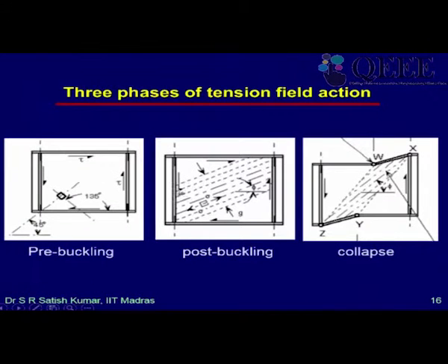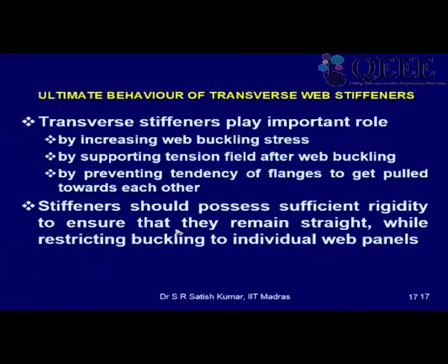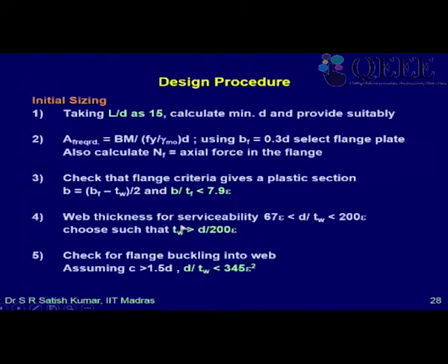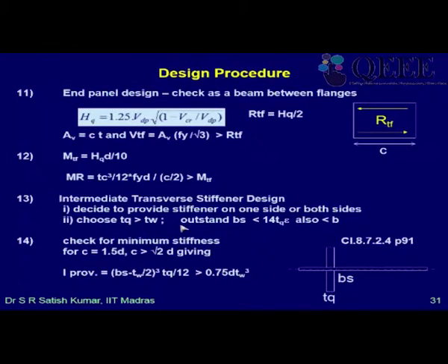Okay, let's say this is my stiffener and the web is extended beyond the stiffener. So I can take 20 tw this side, and whatever is the extension that I can take on this side, limited to 20 tw. Okay, so that I can take. And then this plus-shaped cross section, that is, if I have stiffener on both sides, then it is like this, plus web on both sides. In many cases I'll have stiffener on one side and only web on one side.